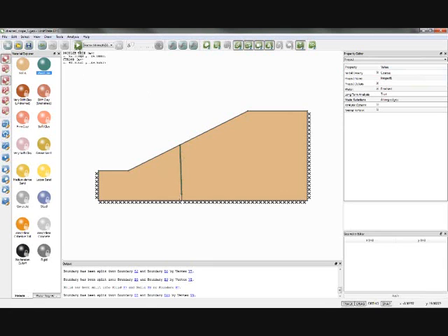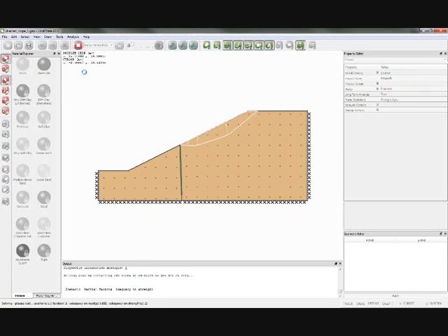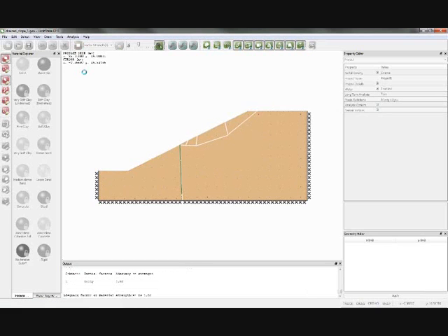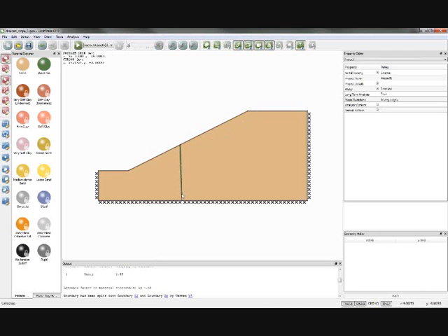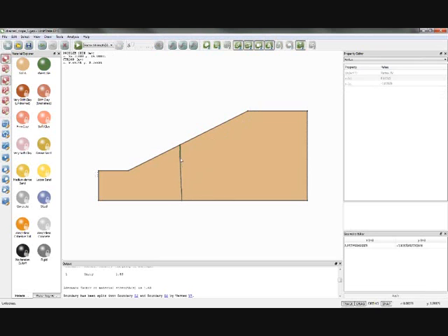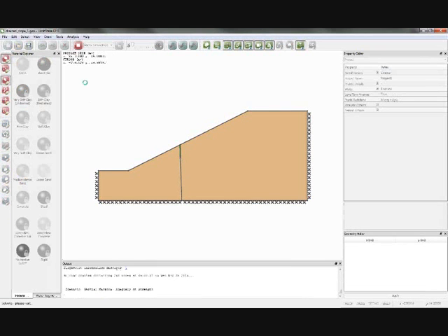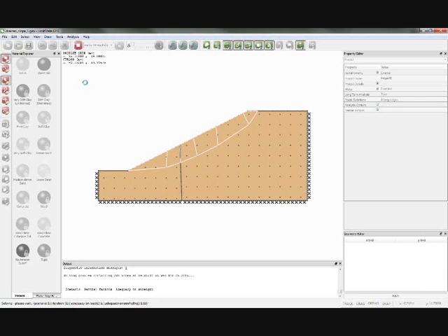the soil. So if I now click solve, the slip mechanism is going to have to either avoid that or go around it. In this case, it's deep enough that it's saying, I can only fail at the top, and the factor of safety on strength has gone up to 1.88, whereas before it was 1.63. If that becomes too short, then clearly it's not going to have any influence, and the failure mechanism will just go around it, and we'll get a number pretty close to 1.63 as before.